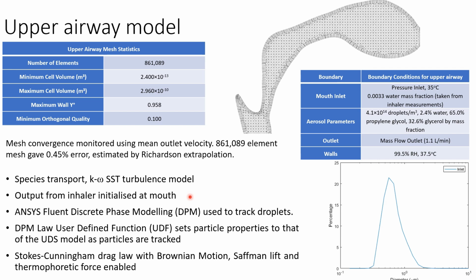The output from the inhaler was initialized at the mouth, so this particle size distribution was used at the mouth. We used Ansys Fluent's discrete phase modeling module to track the droplets, and within that a user-defined function to set particle properties to those predicted by the droplet growth model. Stokes-Cunningham drag law with Brownian motion, Saffman lift and thermophoretic force were enabled.